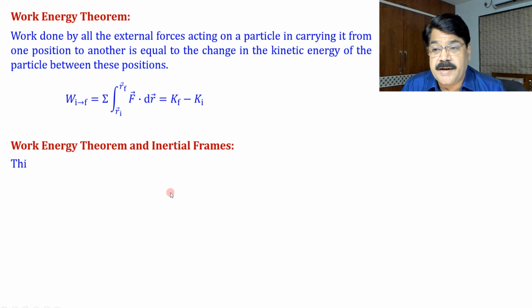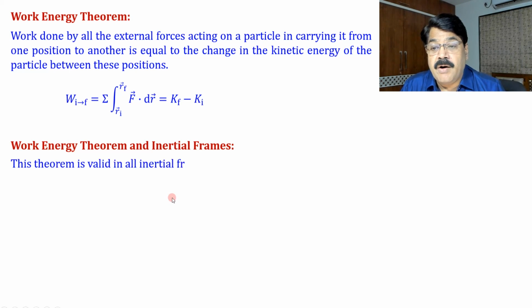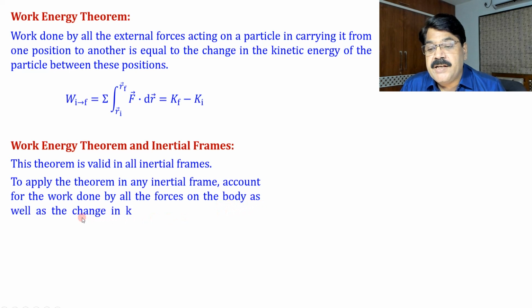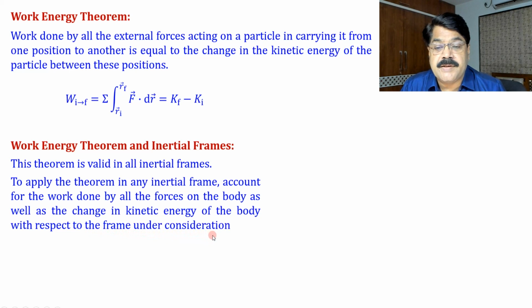And let us document this idea. This theorem is valid in all inertial frames. How is it made valid? To apply the theorem in any inertial frame, account for the work done by all the forces on the body as well as the change in kinetic energy of the body with respect to the frame under consideration. It means if you apply the work-energy theorem in some other inertial frame, what do we have to do? Consider the work of all the forces in that frame which we are considering, and the initial and final kinetic energies in that frame. Similarly, we can extend our idea of how to use the work-energy theorem in a non-inertial frame.